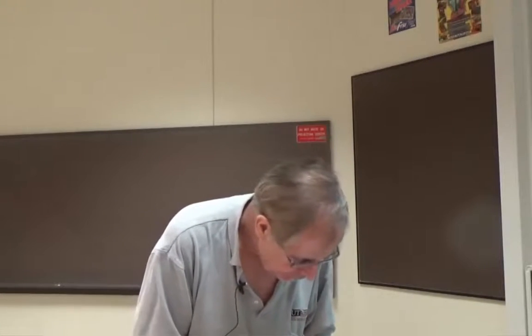All right, questions? Yeah. So you said that you are using input capture for tracking the speed. So do you think it would be better if we use ADC, or is that also going to make a weak link? Okay. Mahesh is asking, are there other ways to take that sine wave and get the speed? You could sample it with the A to D converter and do a fast Fourier transform on it, capture out the fastest frequency.